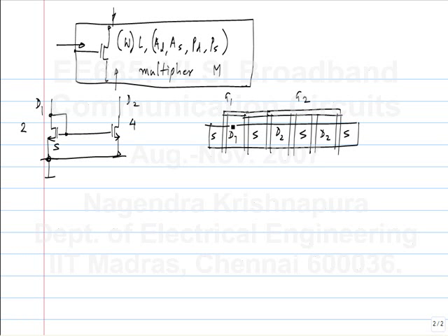Okay, and also in fact the drain is connected to the gate. So this way you compact the area. If you just separate it, it's pointless, and also the matching will be better when they are closer to each other. And on top of it, if you look at it, the very last transistor has no neighboring transistors. The ones at the ends. The ones in the middle have transistors on both sides. The ones at the end have transistors only on one side.